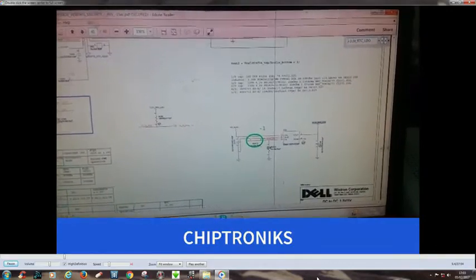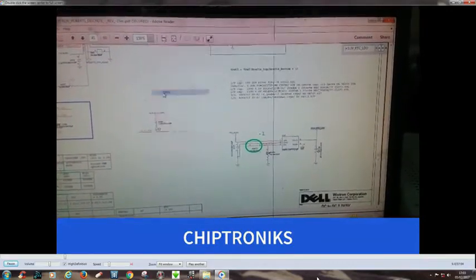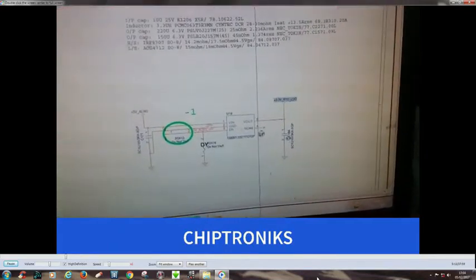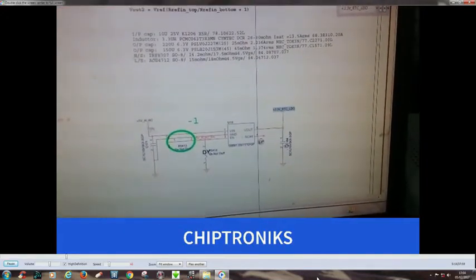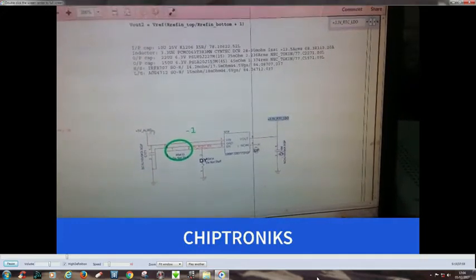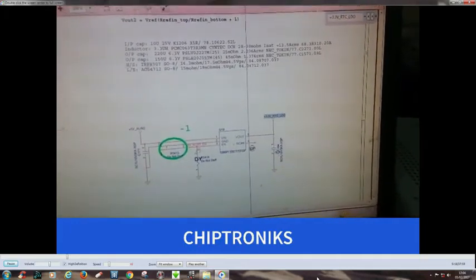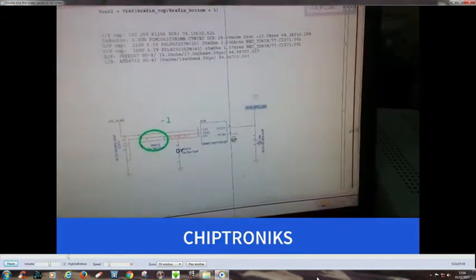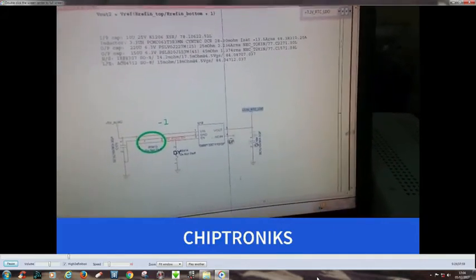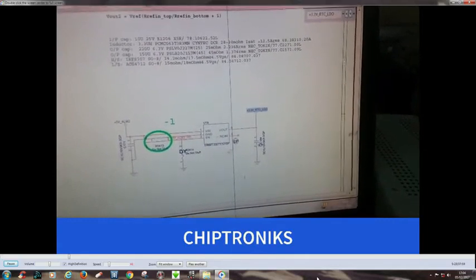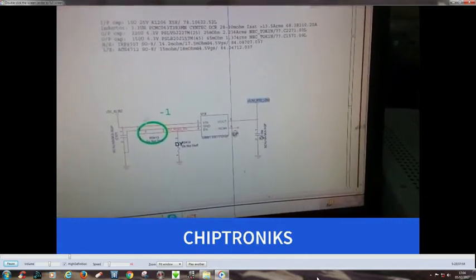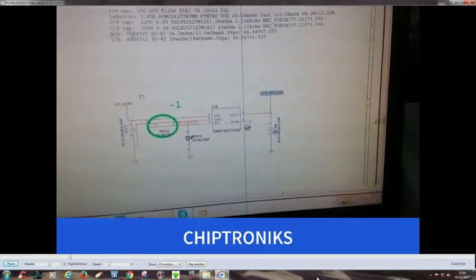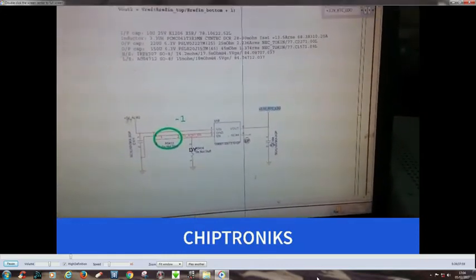You can see this is a small IC, U19. The VIN is connected to plus 5V ALW2, and enable is also connected to this, and this is giving you output. If this is not coming, we have to check this capacitor, and we have to check the input of this IC, that is plus 5V ALW2, and from where this is coming.